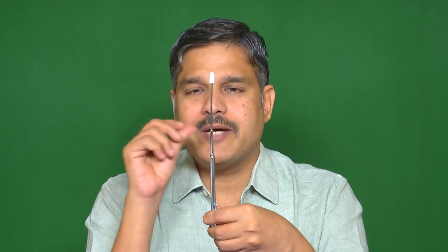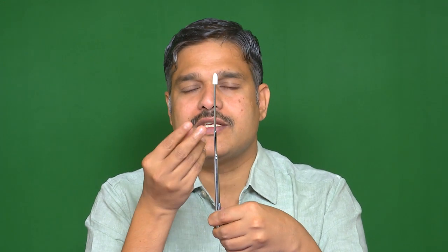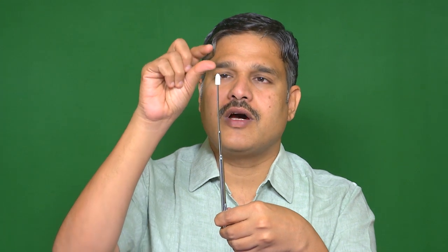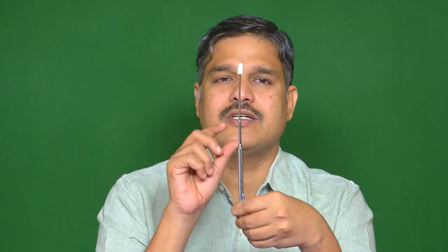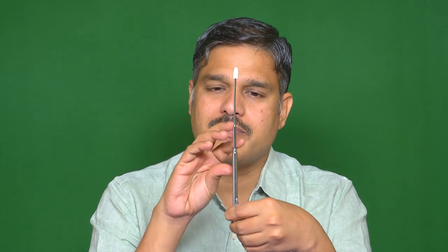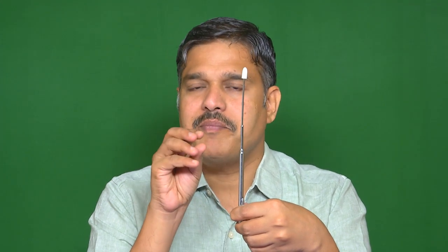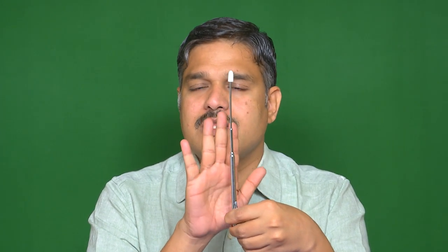The tuned mass damper tunes the frequency of a secondary structure, which we install either on the top or anywhere in the structure, so that its frequency matches the frequency of the primary structure. Using these two, we derive the damping that needs to be present in the secondary structure, because the damping already present in the primary structure is insufficient to control the vibration. This is the main concept of the tuned mass damper.